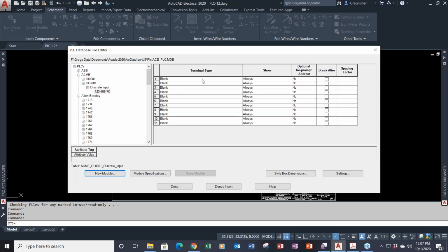The reason is, and I'm going to do this 2 different ways. I'm going to create it so when I insert it, I don't include extra terminals or unused terminals. And then I'm going to insert it with unused terminals, hence the extra rows. And that's the part that can get confusing because it has the ability to include unused or extra terminals when you insert it. When you set it up beforehand, it can get a little bit confusing at that point.